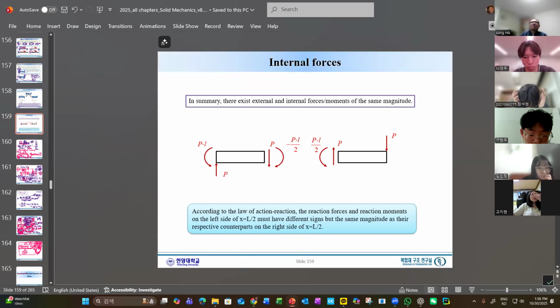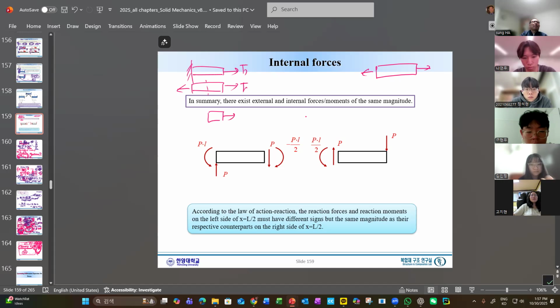Don't consider what the hell the internal force is. It's not a difficult subject. Simply, say we have a beam, a bar, subject to a load. It's very simple. And then what do we have? We have a reaction force at the left from equilibrium, right? Once we have this, what do we have here? You apply F, there will be an F here, and an F here, and here you will have an F. That is the internal force, nothing else. So everywhere you have a certain force.